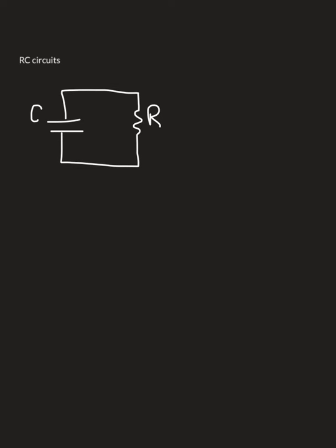There's not much that's going to happen here because when we draw the capacitor, we draw it with this gap in between the two plates. That's not just a style choice, that represents something physical about what's happening at the capacitor. There's no electrical connection from one plate to the other, there's a gap here, which means this circuit is not actually a closed circuit, it's an open circuit. And when it just sits here like this, we don't actually expect charge to flow.